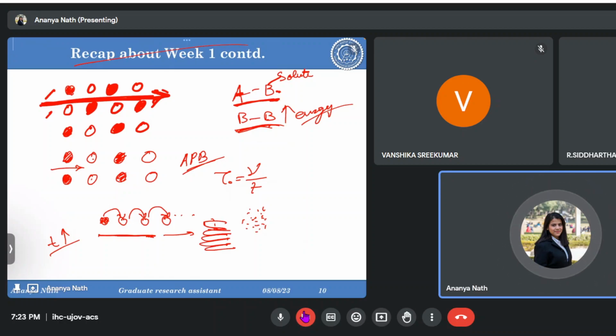When the velocity of the dislocation is very high and the solute atoms find insufficient time to rearrange, in that condition solute atoms are considered as clusters, and they will act as an obstacle to that dislocation.